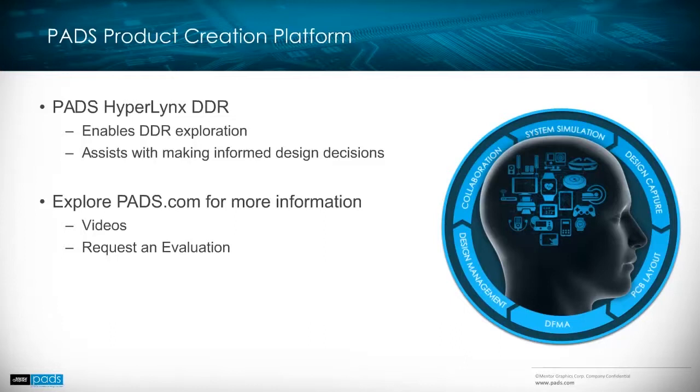In this web seminar, I've shown you how you can use PADS to explore DDR circuitry to ensure proper placement, routing, and termination. I've also shown how PADS Hyperlynx DDR creates a nice report that makes it easy to see where a design may have failed to meet timing or voltage requirements.